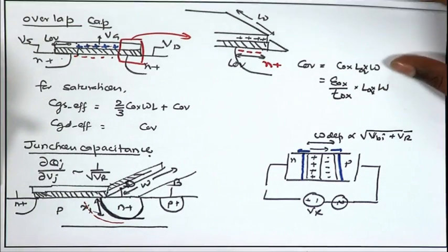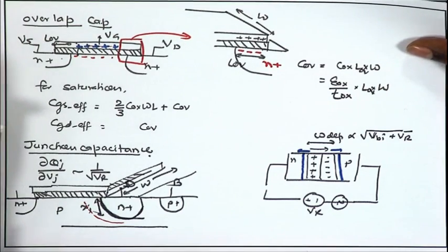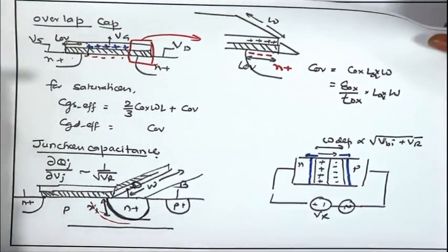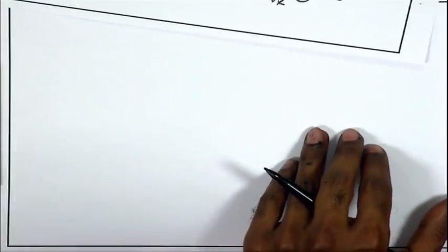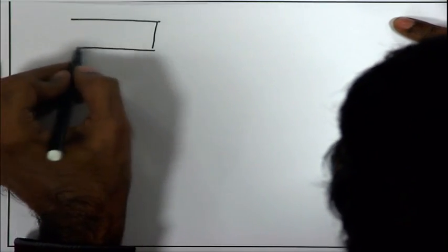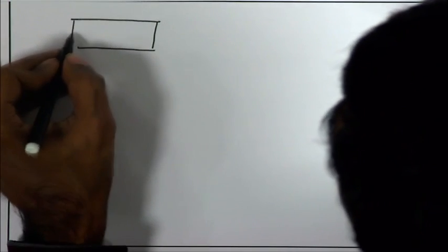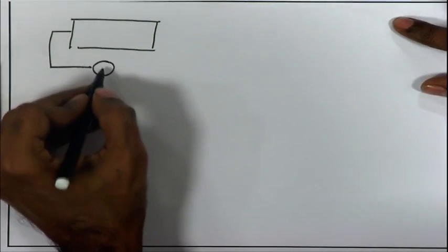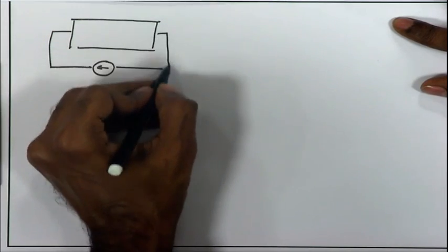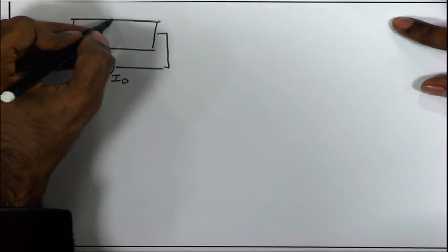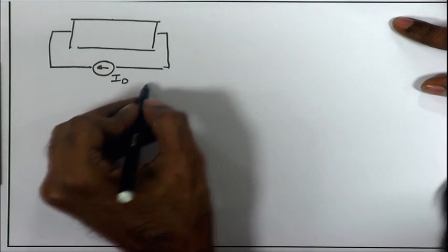small signal analysis. So, for example, if I take this diode, and as I said, I am injecting a current. Suppose I am having a DC current source across this diode. So, I am putting some DC bias, call it I diode, and we know that there is an exponential relationship.